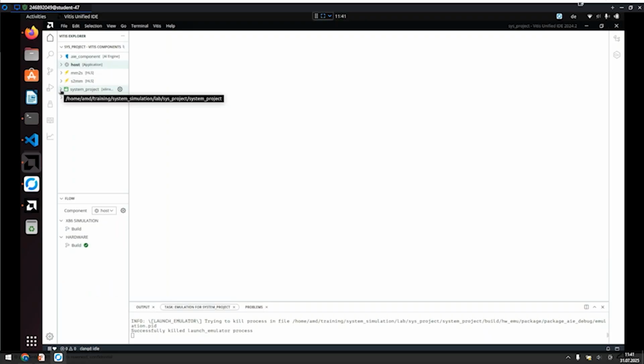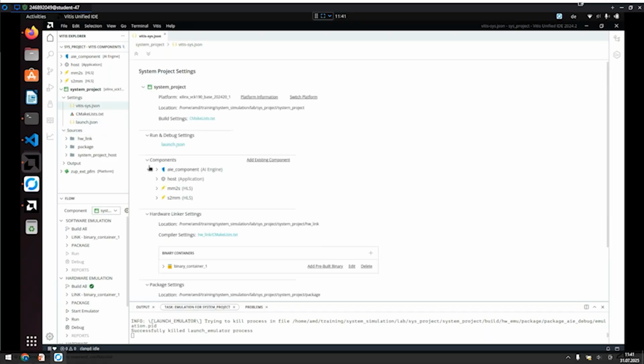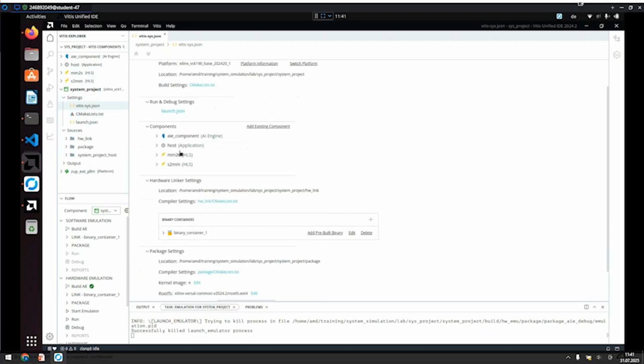What we have to do then is to define this linker step that I was mentioning before. And the linker step by itself is actually created by the settings in our design. So the linker step picks up all of these items, and I can bind them together in one executable or one library level file, which is a particular file format that Xilinx is using to combine these things.